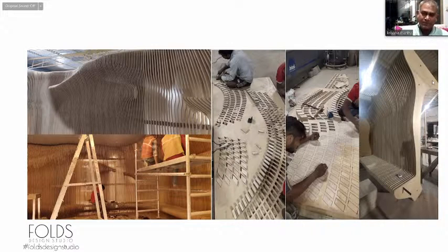We did a lot of research, and then we made sure that, because we wanted this tool to be rectangular, you can see the individual piece there. It has an outline which has no corners. Those corners are just 1 mm. If you cut in CNC, you get a 3 mm radius circular cut at the edge, which we didn't want. So we cut this whole ply in water jet so that we could get those exact sharp angles, and they could be placed as a spacer in between the vertical slices, so that it becomes much easier for us to join.